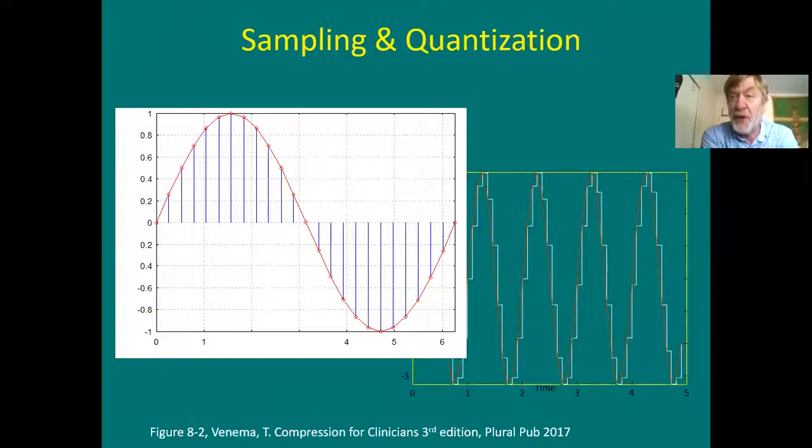Okay? The purists are saying the white wave has lots of little jiggles and steps in it, and it's made by sampling and quantization, such as is done in digital processing. But the real audiophile, the real purist, is always going to stick to the analog. Now, there's truth and there's falseness in that, okay? Because in general, sampling and quantization have gotten so good today that the white waves have way fewer steps, and they look almost just as faithful as the red wave. We've improved our sampling and quantization quite a bit.